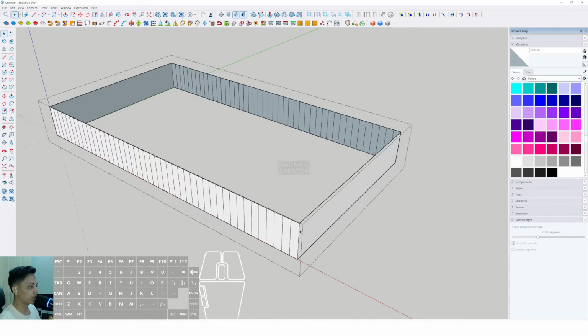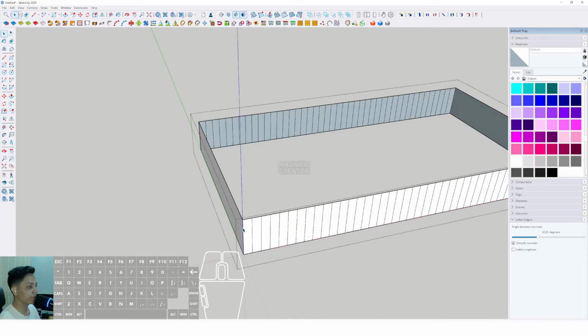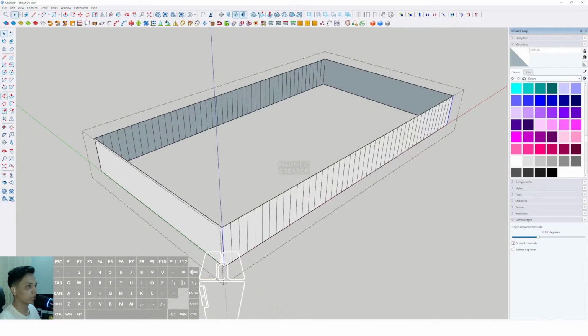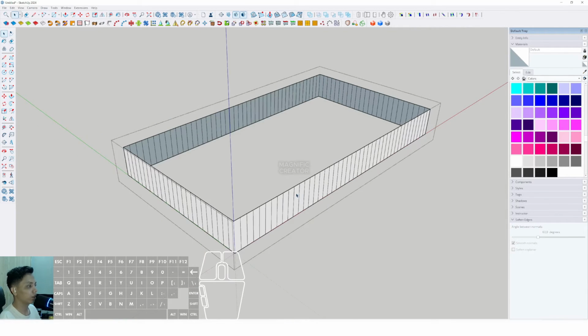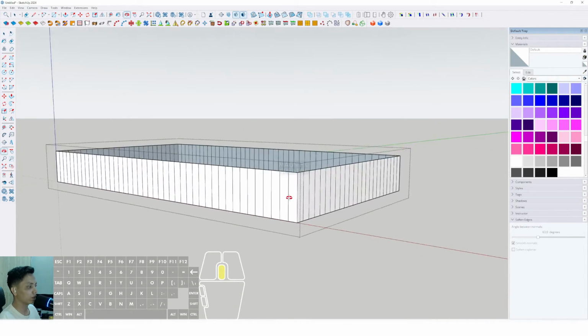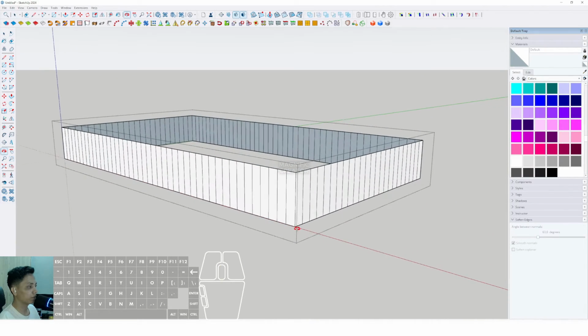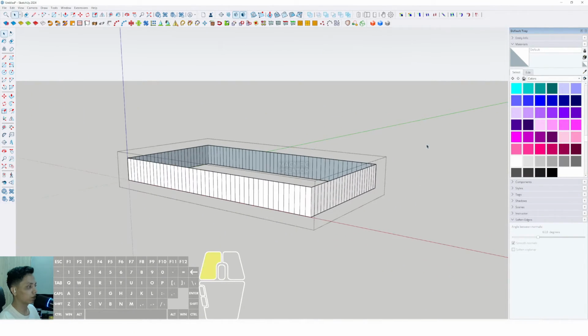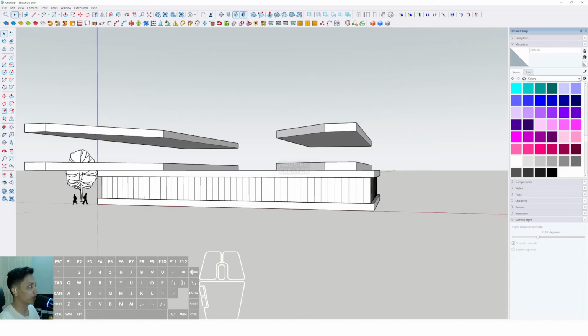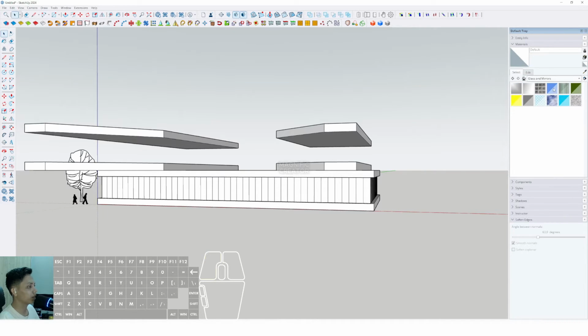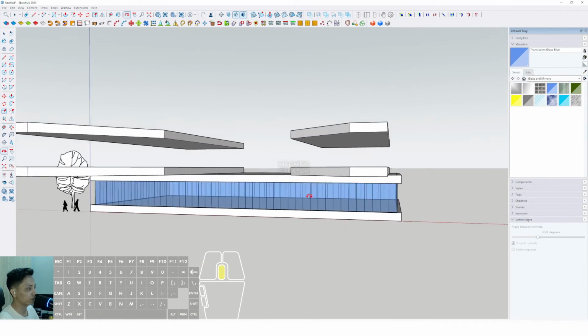Okay, then we can click this right side line and left side line. Then we can select Move, press Ctrl, and click from this corner to the corner behind it. Then we can type 24/ and enter, and it will be automatically arranged as the vertical frame schematic on this glazing system. We can also change the materials using the blue glass material here.